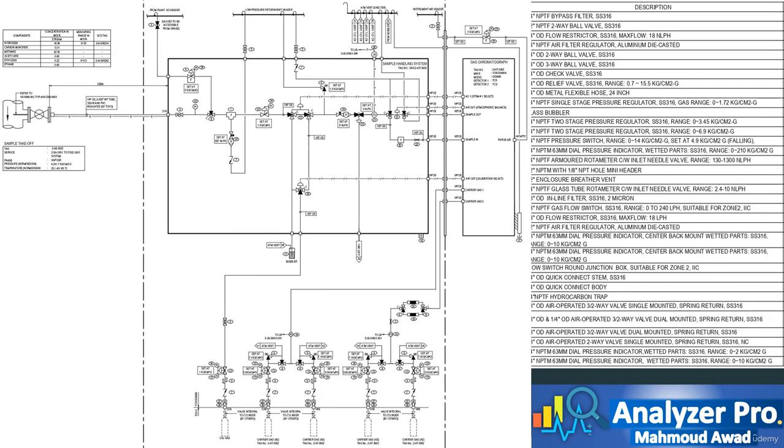This example is exactly as the previous one, except that the sample line is PVC isolated for personal protection. We can see that the process temperature can reach -45 degrees Celsius, so we must isolate the sample line to prevent ice formation on the sample line and to protect any person that can touch the sample line.